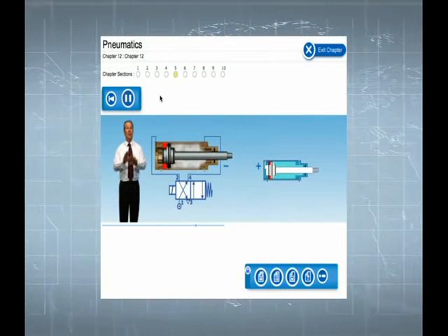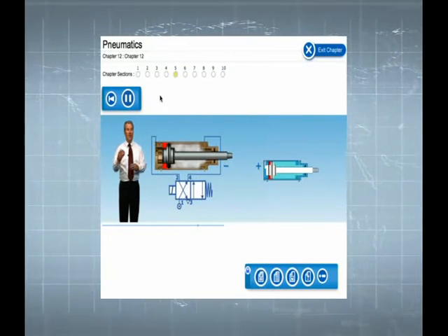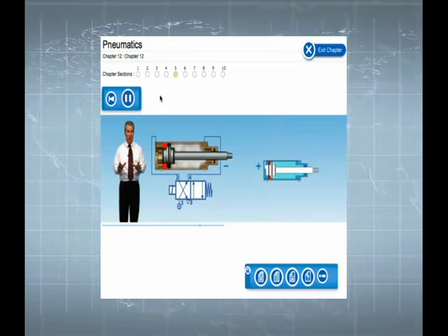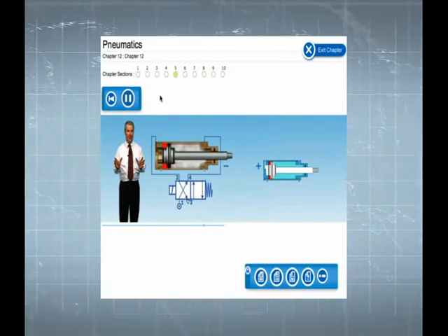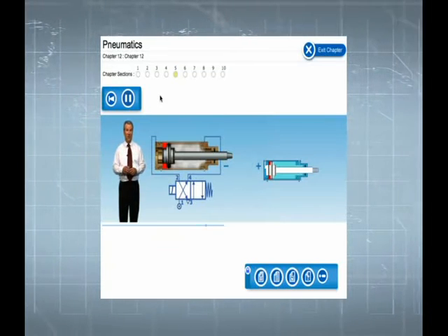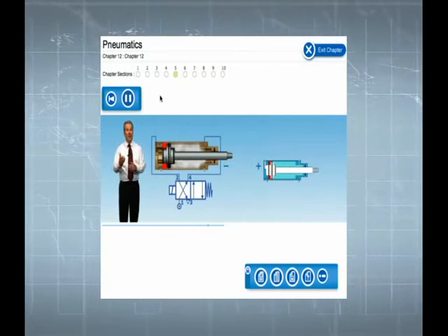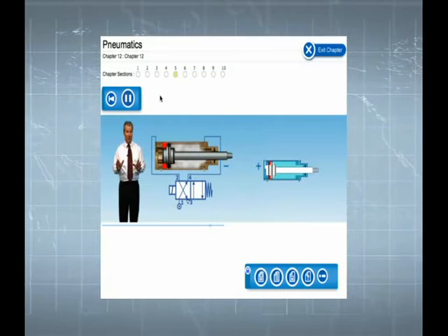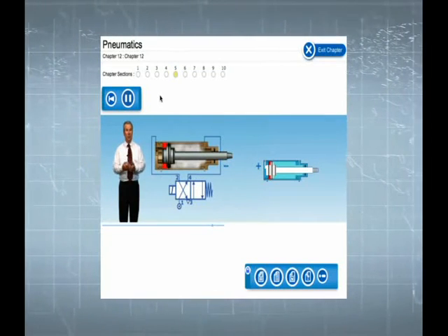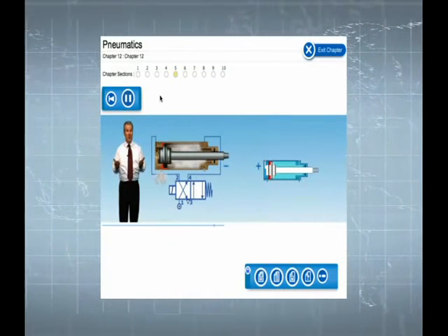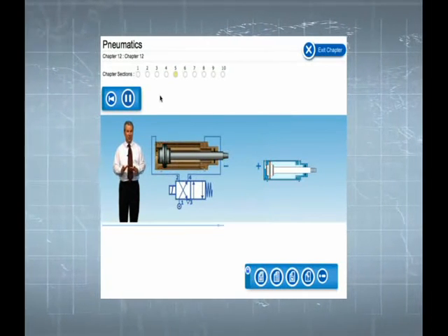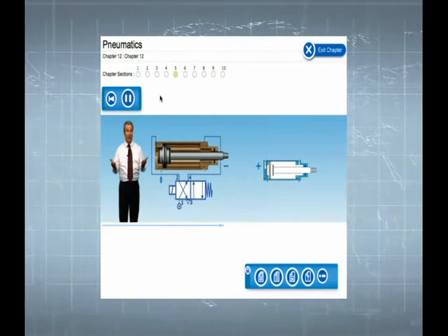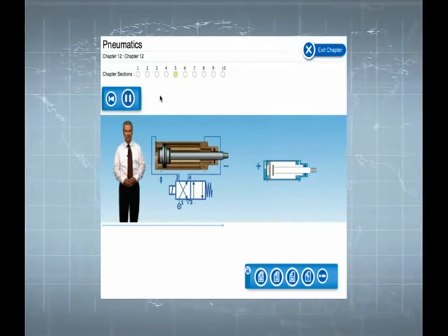With the vent completely closed, the end movement of the piston rod is cushioned by the trapped air. If full cushioning is not required, variable cushioning can be applied by controlling the rate of exhaust of the trapped air. This is achieved by adjusting the size of the vent aperture as shown.